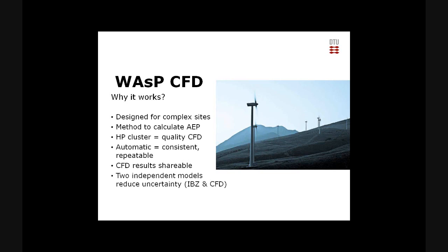Finally, you now have two independent flow models in WindPRO. You have what I call the IPZ model, which is the traditional standard linearized model, and you have the CFD model. So by having two models, you can get two independent results, and that helps reduce the uncertainty of your wind resource predictions.